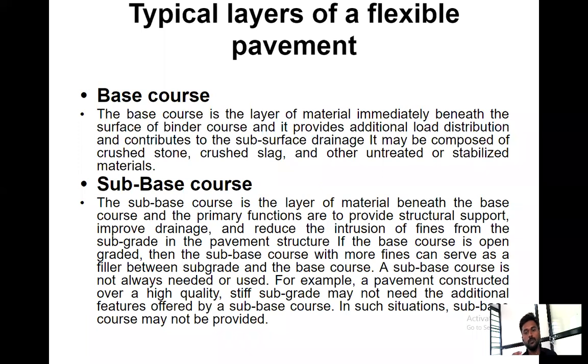Then the subbase course will be there. The subbase course is a layer of material beneath the base course, and its primary functions are to provide structural support, to improve drainage, and to reduce the intrusion of fines from the subgrade into the pavement structure. What is the purpose of the subbase course? To provide a proper base for the base course and also to transfer the load coming from the base course downwards to the subgrade.